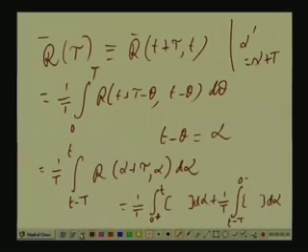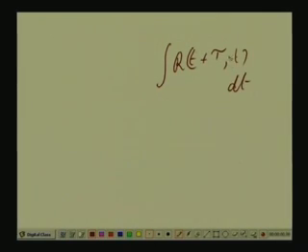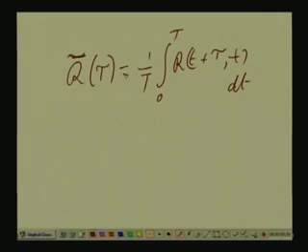That result is a function of tau alone. What you get is r; you can call it alpha, or you can bring back t again, it does not matter, because that is an integration variable, 0 to T, 1 by T. This is your r of tau. So this process is strict-sense stationary.